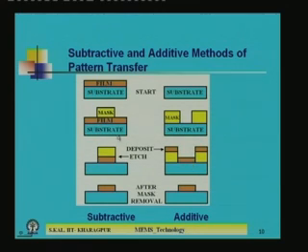Not initial silicon dioxide, then photoresist. First photoresist is deposited, then pattern, then we deposit either the metal or silicon dioxide here. That is the film. Now what we do after this, we just dip the structure into a photoresist removal solution. So, if you dip the whole thing in photoresist removal solution, what will happen?